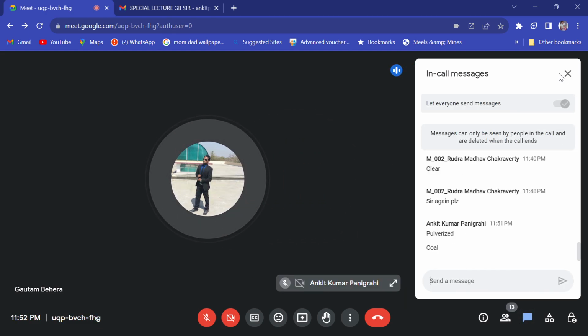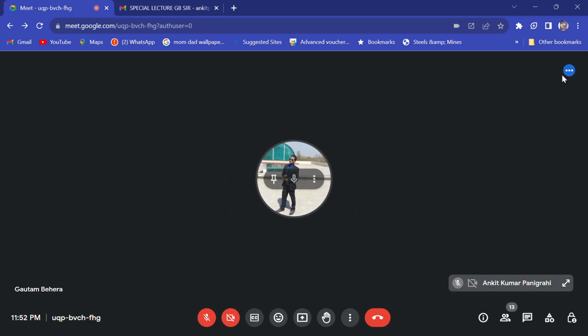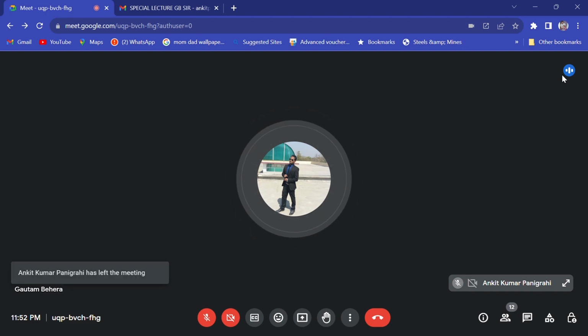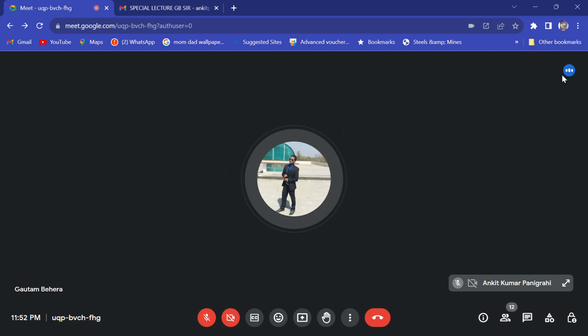Can you tell me which one is a better reducing agent, hydrogen or carbon monoxide? No, hydrogen is a better reducing agent. Hydrogen is 5 to 6 times better reducing agent than carbon monoxide. You have to remember, because of its small size, light weight, and its utilization. If you check the percentage, hydrogen utilization is very high at high temperature, like 900 or 1000 degrees centigrade.